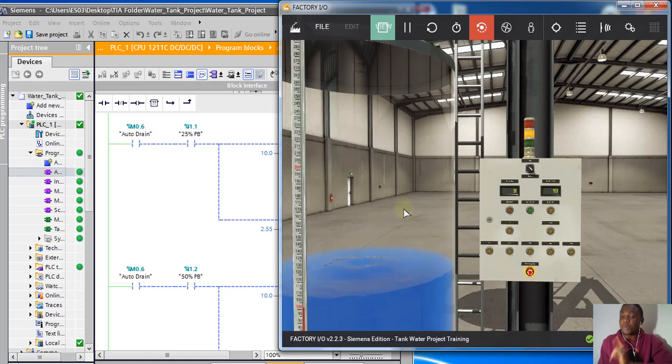But the valve didn't stop at once because it's a proportional valve, like I told you. It closes gradually. So you have to create some tolerance for that. So in order for me to bring the system back again, I have to release the e-stop, but it's still blinking. So after removing the e-stop, I need to acknowledge that I have removed it by using the reset push button.